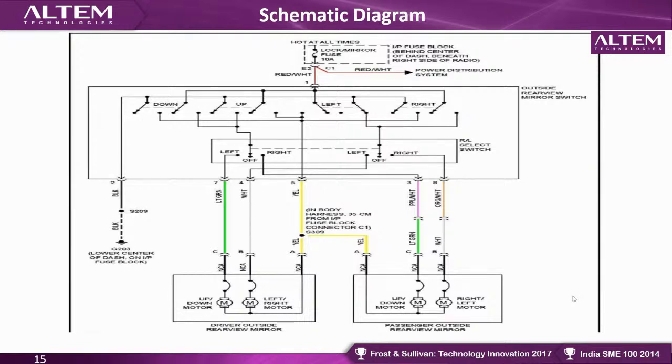It is a line diagram which will show where there will be a connector, where there will be equipment, how the harness will flow, what will be its connection point, where will be its termination, which harness will go into which connector, which harness will go from equipment to connector or from equipment to equipment through a set of connectors, where the supports will be required, and what will be the length between two connection points.